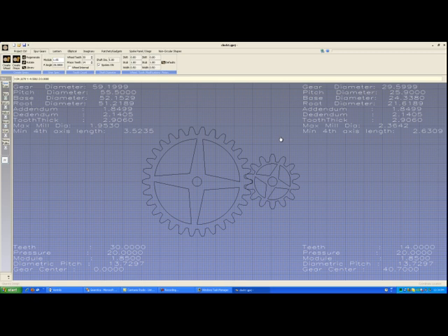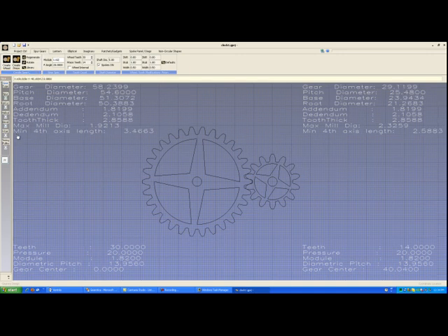Well, that's too big again because we had 40.2, and what we'll find is at about 1.82 we now have a center distance of 40.04. We wanted 40.2, we have 40.04. That leaves 0.16 for backlash, and I like around 0.2 millimeter for backlash. So these 2 gears are absolutely perfect, and they would fit on the center shafts.